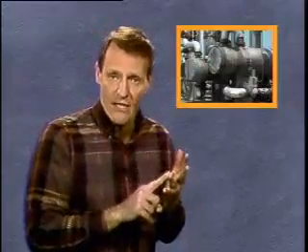If the source of the gas is the process, there may be a problem with the process or with one of the components in the process. In this topic, we looked at some of the basic problems that can affect a typical heat exchanger, including fouling, tube leaks, and air and vapor binding. We also looked at the causes and effects of these problems, and we saw how they can be dealt with. Let's take a moment now and try some practice questions.